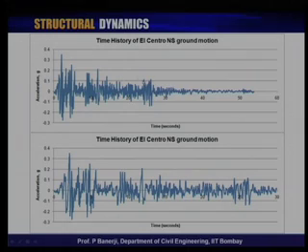So, this same thing, just this part has been zoomed up, and it gives you a better idea of how the shaking occurs. It starts, then it builds up, and then you get the peak. The peak ground motion in this particular case was 34% of g, which basically means 3.4 meters per second squared was the approximate ground motion. The peak ground motion happened about 2.5 seconds into the motion.